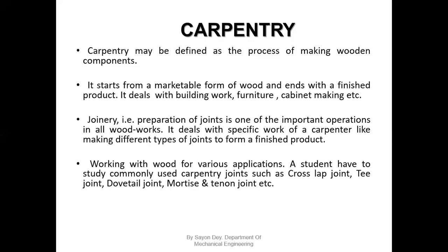Okay, I'm not discussing in detail here. I'm going to give you the overall overview about the workshop practice. But I'm telling one sentence about the pattern shop. Pattern is under the carpentry, but this is different. Basically, this is the model or replica of an actual object that is to be cast. If we want to make any metallic object through casting, then we have to make a model of that object, and that model is called the pattern.